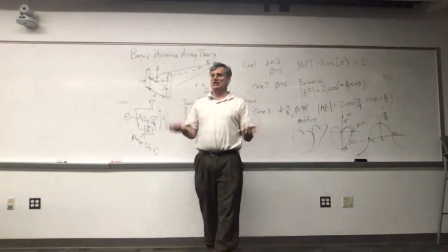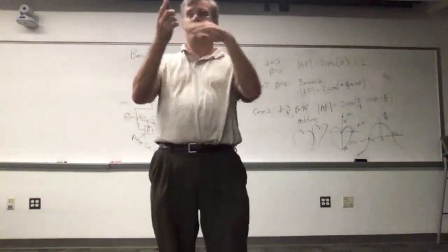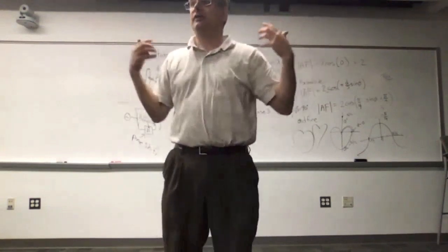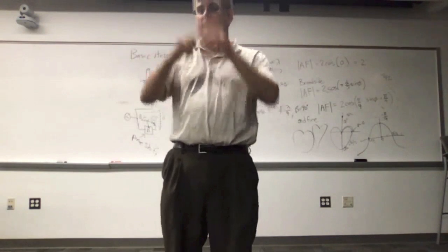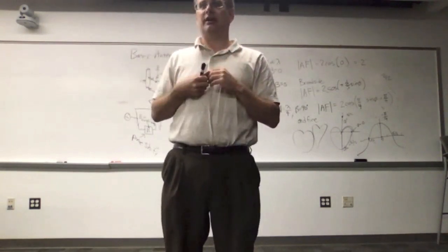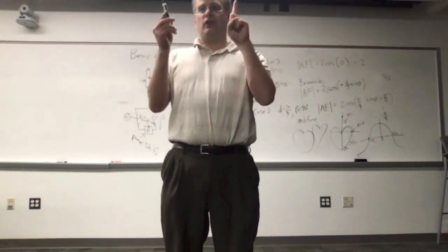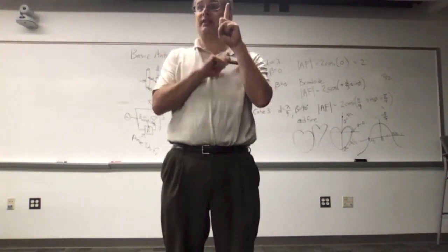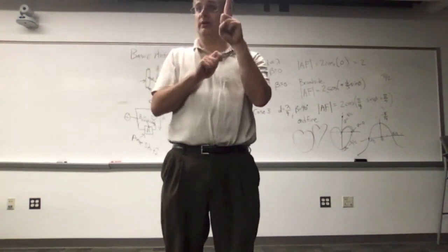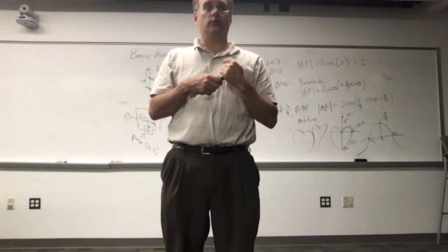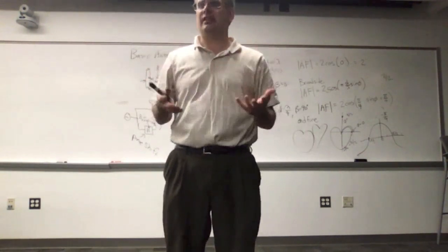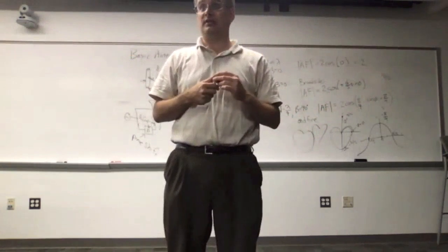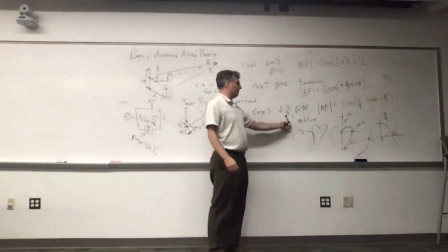Another thing from a receive point of view is if I have two antenna elements and I'm bringing them close together, remember we said there's an effective electromagnetic aperture around those antennas that gathers field strength from a wave and absorbs it and carries it to the transmission line it's connected to. If those effective electromagnetic areas start to overlap, then that antenna is stealing some of this guy's power that he would have normally used to pull in and excite his load, and vice versa. And that will do crazy things with the pattern of the individual elements, as well as the collective system they're being used as an array. So lambda over 4 is uncomfortably close, but we still do it to get to things like n.